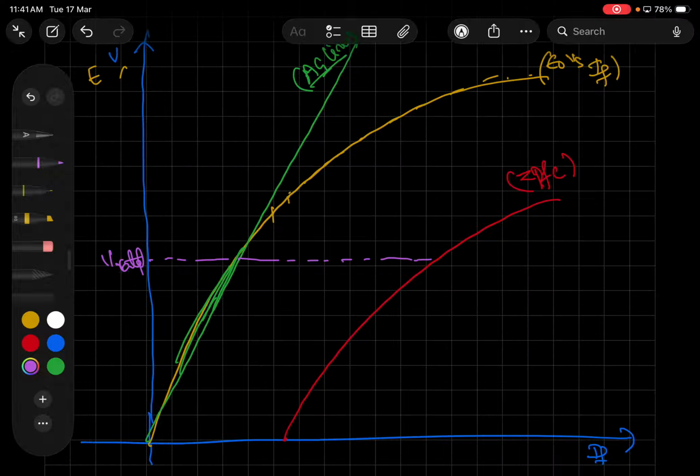Always convert this rated voltage into phase manner. If the line voltages are given, convert that into phase voltage and draw a dotted line onto the ZPFC curve here. And next, give the notations here. From this, give the notations as OA.